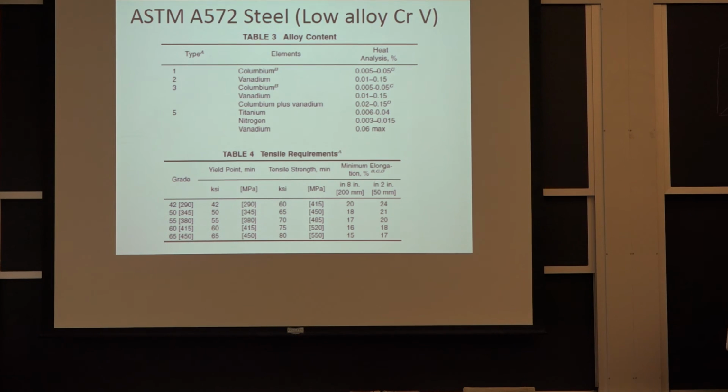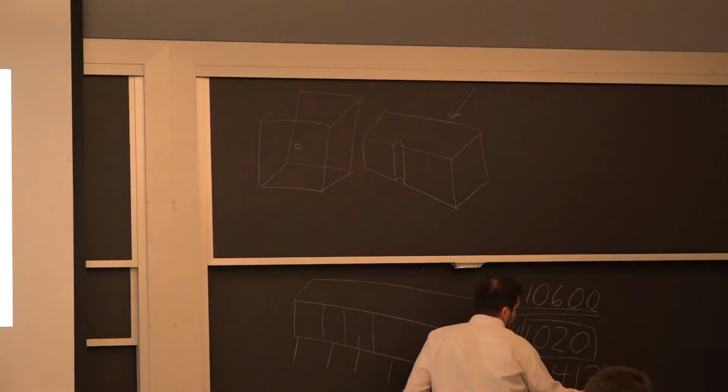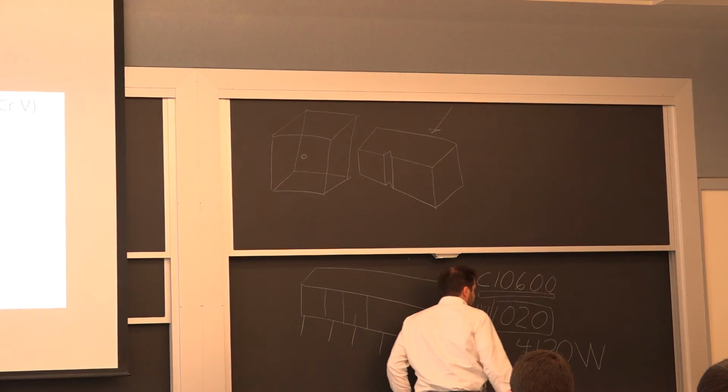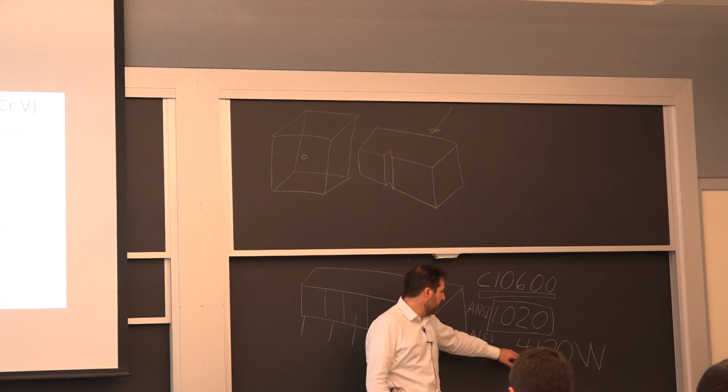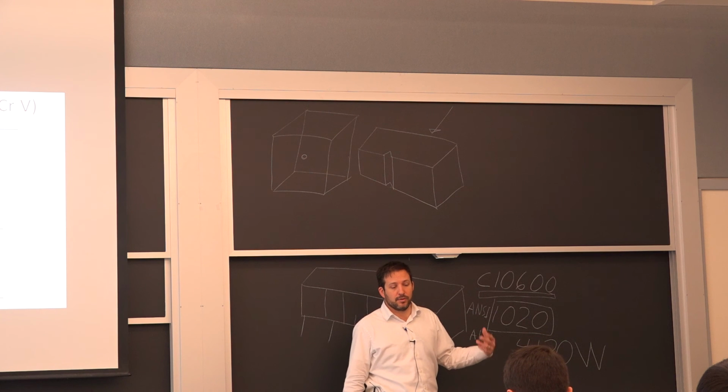These do tend to be ASTM standards as opposed to AISI or CDA, Copper Development Association, and it's just the way it is. So most ASTM products will have not only a makeup requirement, but also performance requirements, and specifying those is a big advantage. So if you're building a go-kart for racing and you ask for a 4130 steel that can be made weldable, so you ask for a W grade of it, it's the same story where you're just saying the chemical composition you want. You should ask for this as part of an ASTM standard for the product.